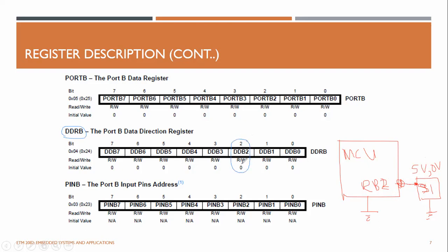And now it is input, right? Already input, because the 0 is written. Or sometimes you can just overwrite it as a 0 again, right? Doesn't matter. So you write 0 here, so it will act as an input. So it is high impedance from this side.